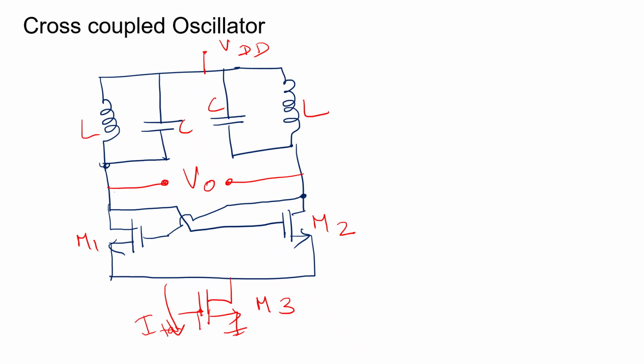When M1 and M2 operate differentially, the common source of the transistors is virtually grounded. The total thermal noise produced between their drains and sources contributes to the output. This noise is converted to excess phase and produces phase noise. The optimum phase noise occurs for I tail at the boundary between the current and voltage limited regimes.